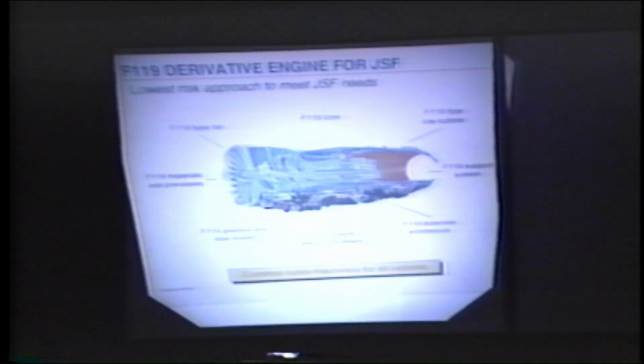We know where we've gone awry in some of the spots. That will be changed in the F119 when they get in the ISR, so we've improved the fan a little bit where we had some separation. They're going to have better performance. We want to use common materials. That helps us in process. It's going to help us in cost and works quite well. Gearbox and lube is going to be the same as what we had in the F119.